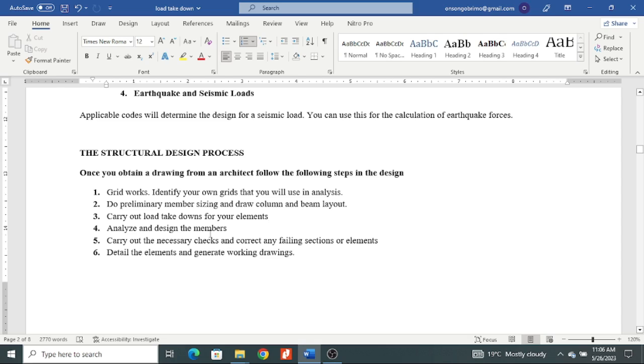Now after you have the load that is acting on the member, you have the torsional, the shear, the bending moments, and you can even draw those diagrams. Next you proceed to design the member. Designing the member is giving the exact specifications that are sufficient for the utility of the said structure. If the utility changes, the members could be either changed to be bigger or smaller depending on the change, or it could even fail, because different utilities have different load considerations.